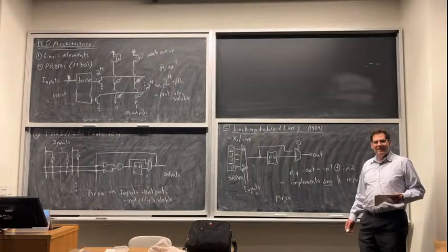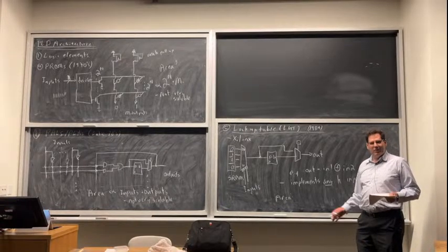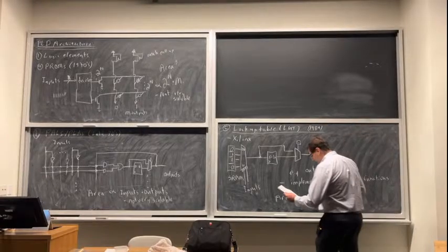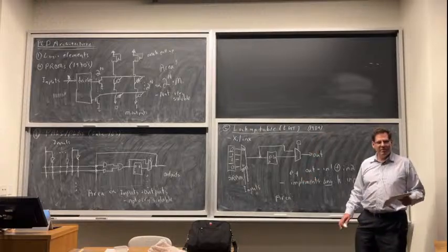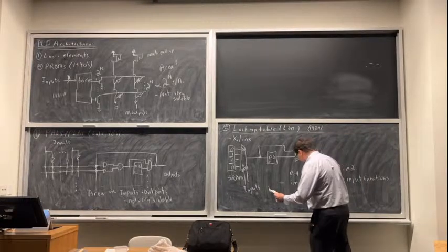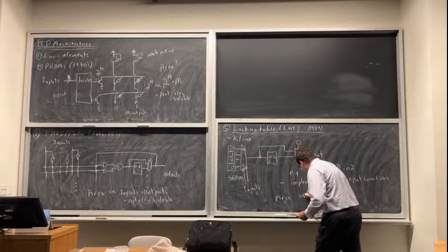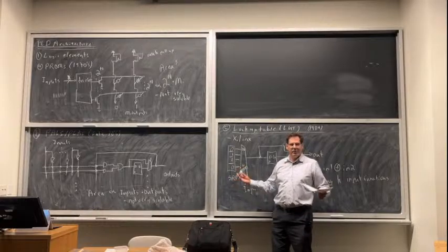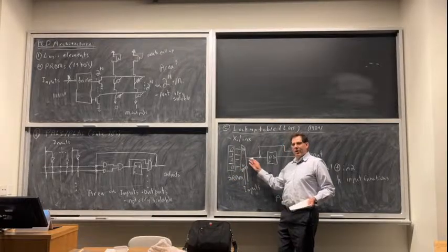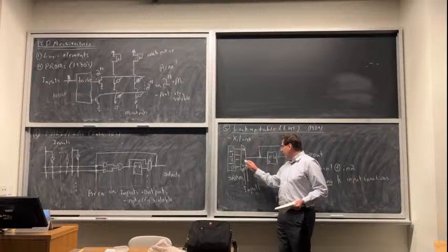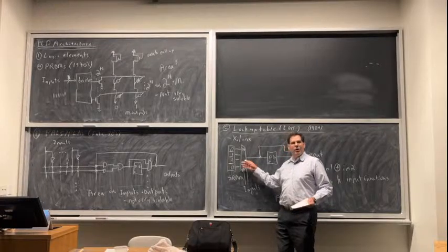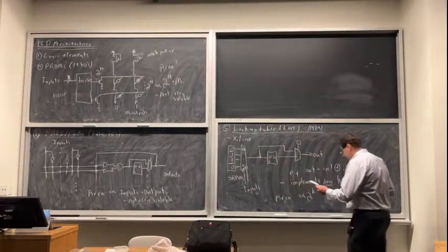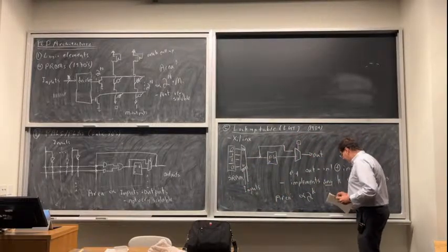What do you think? Linear, square, factorial? Right, so it could be n, but we usually just use k. I'm going to use k for the number of inputs because it's more conventional in the literature. So the area is proportional to 2 to the k. It's because the number of SRAM cells increases exponentially as you add more inputs. If you go inside this mux, which we will do next class, you'll also find that it grows exponentially. When you look at all the transistors you need to build it, this mux also gets bigger exponentially in k. So basically this is also not scalable.